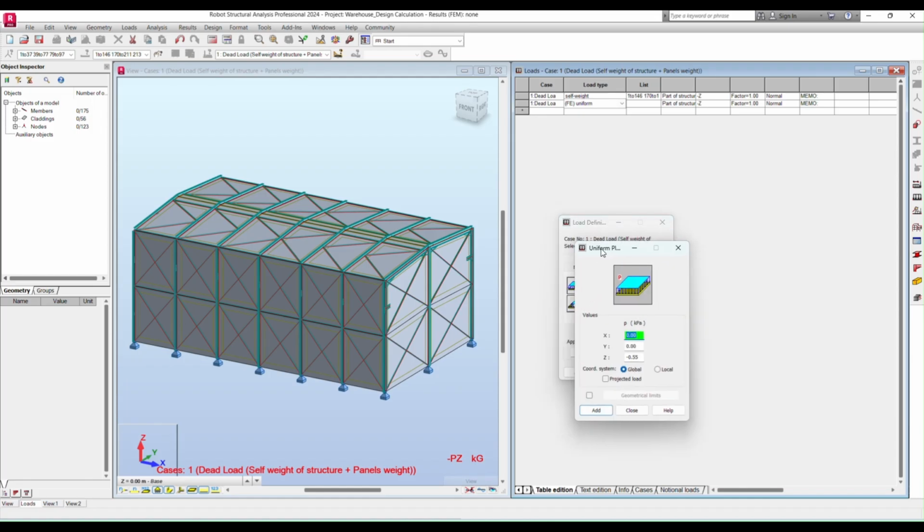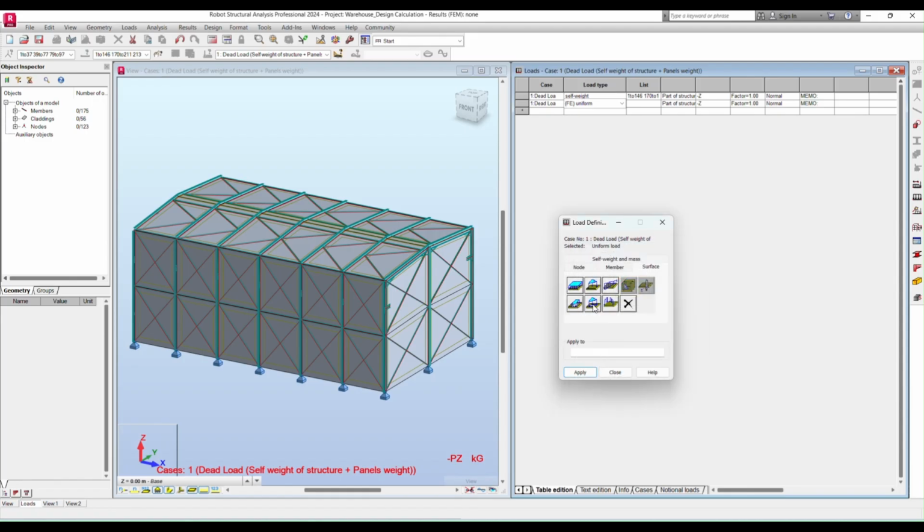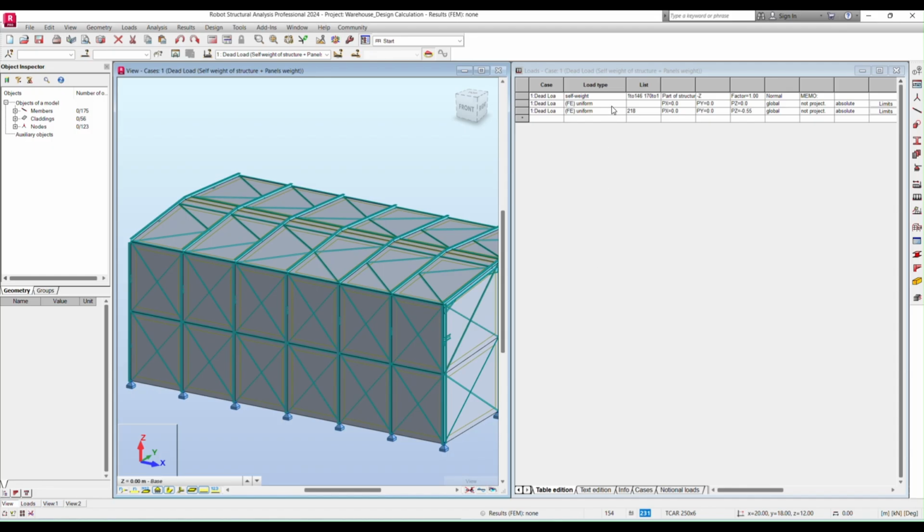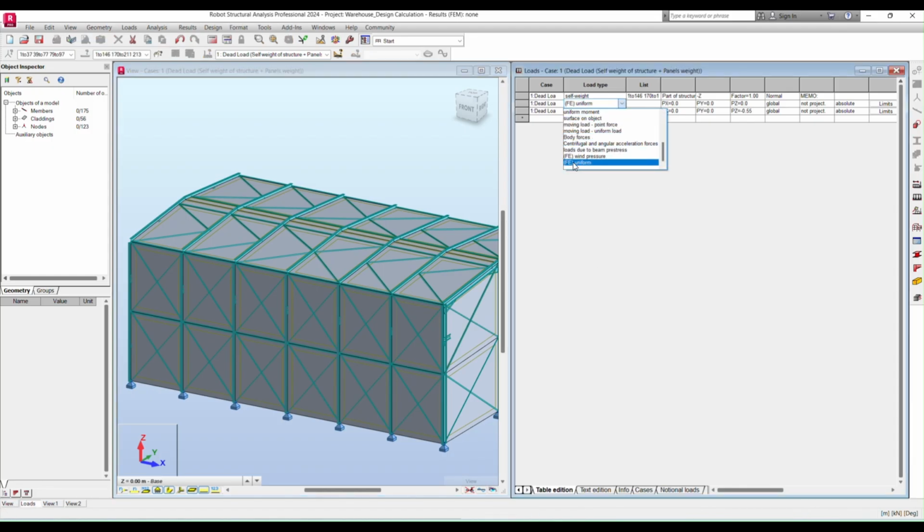So click this uniform plane, and here you can consider minus 0.55 or any value, add it here and pick this value, so that you are able to see the downward force, the vertical forces here for this cladding. Then you can close this, and now you can see this FE uniform in case it is not available there. So now we can delete this sample.